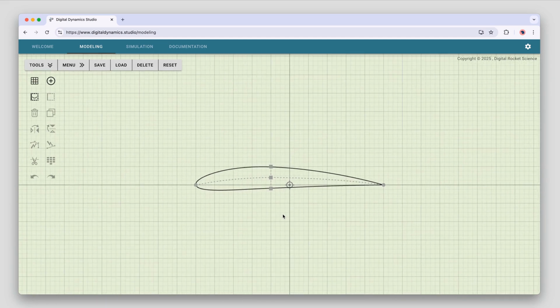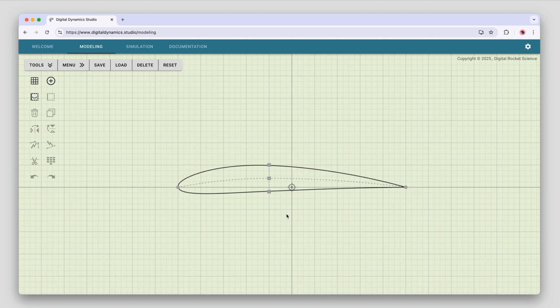There's a critical angle used in wings and airfoils called the angle of attack, and that is the angle of the wing with respect to the main fluid flow direction. What is the angle of the wing? Well, the angle of that airfoil is defined as the line from the airfoil's tip right there to its tail right there. So in this case, the line right here along the x-axis is the wing's chord line, actually. The camber line is this dotted line here. The chord line is the line from the tip to the tail.